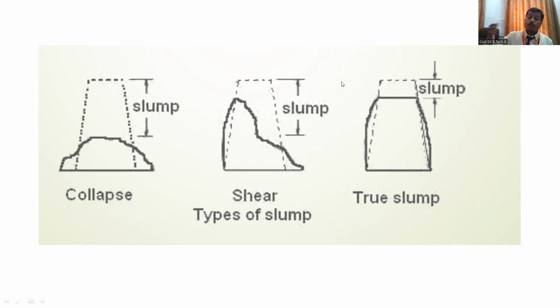But more highly workable concrete will definitely have some adverse impacts on the other hand. Okay, and that is what again we are going to learn in our upcoming sessions. So for this time you just remember what are the different types of the slumps. You are having the true slump, you are having shear slump, you are having the collapse. True slump indicates the slump value is in the range of 0 to 50 mm, shear 50 to 100 mm, collapse more than 100 mm, highly workable.